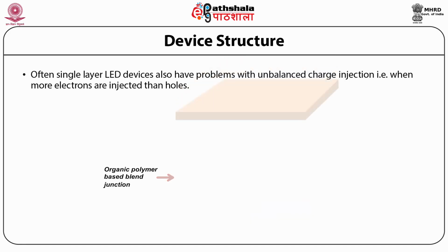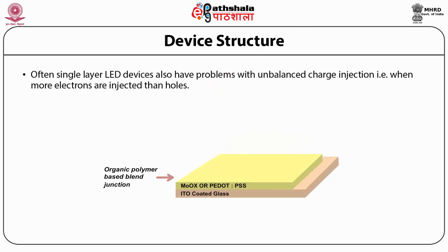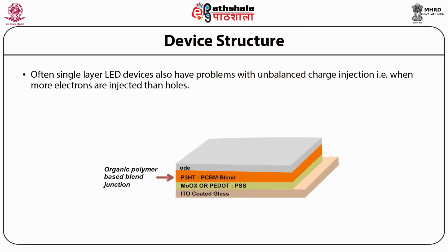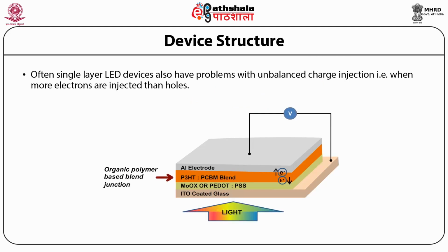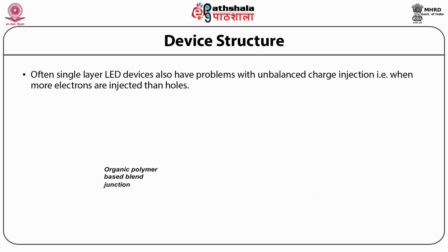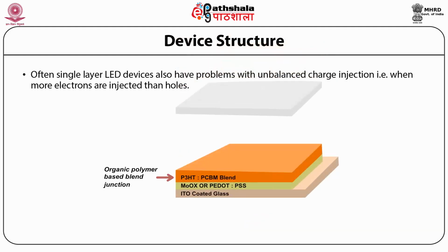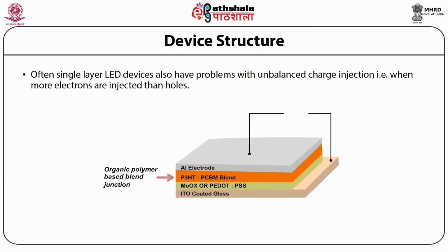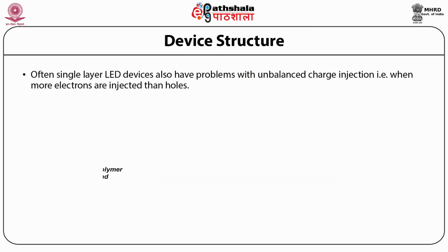Active layer is the organic layer, which can be a single layer, a bilayer, or a bulk heterojunction layer, or some other structure based on the type of solar cell being fabricated. One of the electrodes is typically transparent to allow the light to fall upon the active layer.